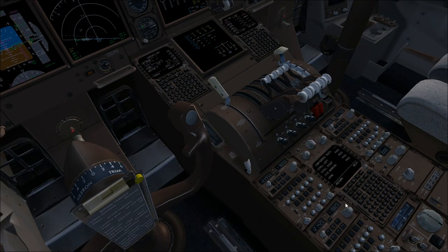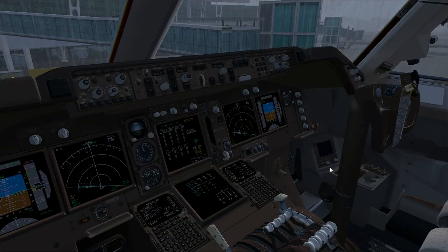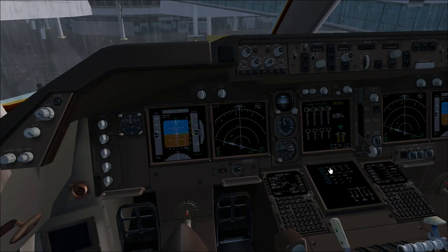So confidence test completed for the first flight of the day, and we return here on the CMCR menu. You can check out the present lag fault in case you have any problem and the status messages during the flight, and you also have a second page where you have the existing fault and, for example, the fault history of the aircraft or other functions possible. Coming back to the CMCR, we will leave them here, and we can start the before start checklist.